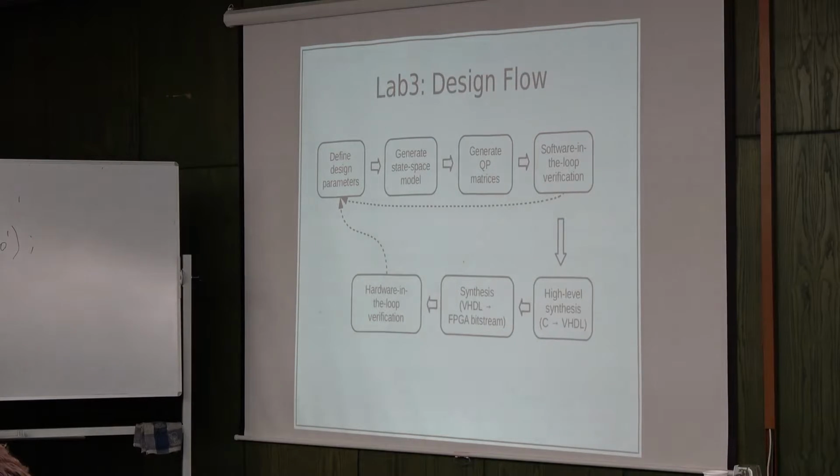However, if at a certain stage you want to open the project and see what is going on, you can do this. You just go to debug mode, and in this case you will open your Vivado or Vivado HLS project, depending on the stage that you are on. You can also handle low-level details. If you are not interested in that, you just trust ProType default parameters and Xilinx tools. And then you have automatic software in the loop verification. All the communications via Ethernet are handled automatically.